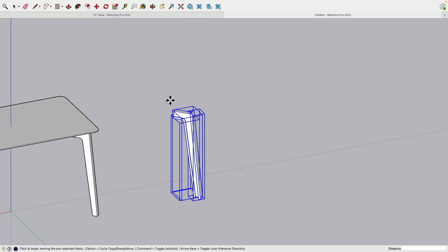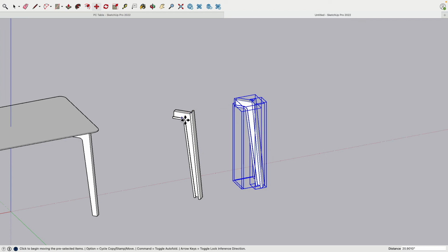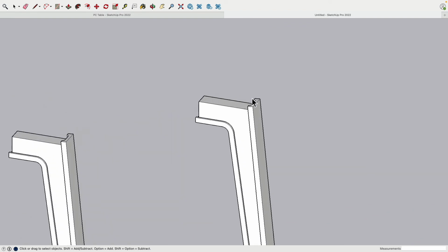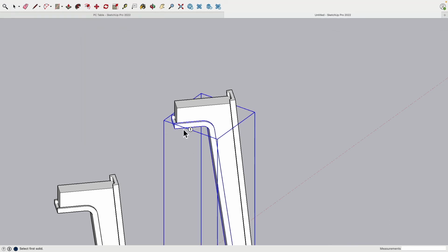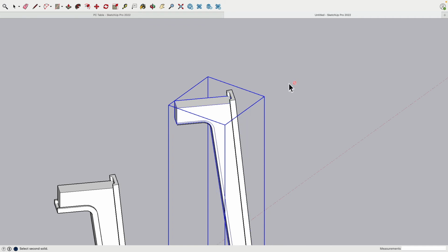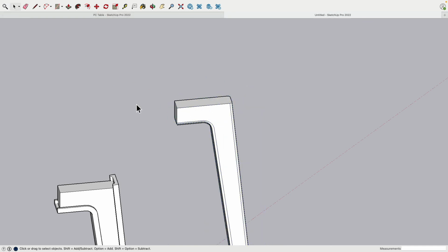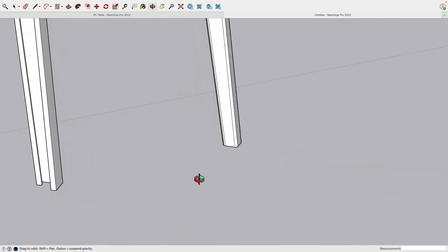We will keep this as a copy, in case we would want to go back and modify these details, then we always have the raw source. And now we will go to solid tools, subtract, and say the tool from the target and the tool from the target. So that's the sequence. Yeah, look at this. It's actually quite beautiful.